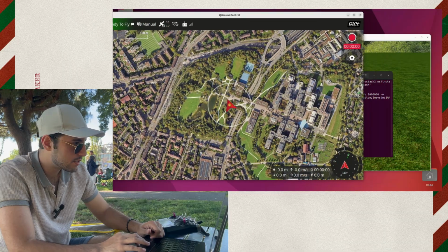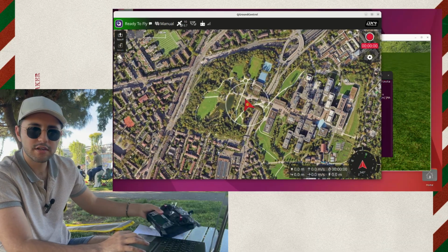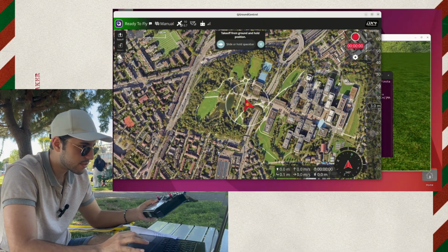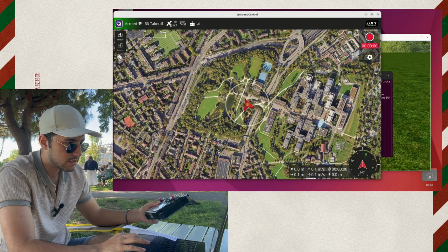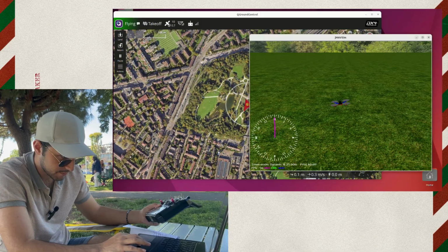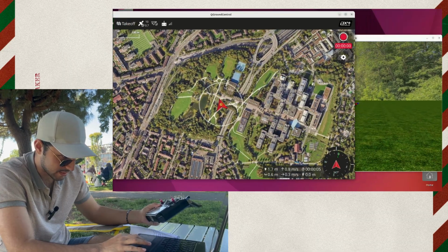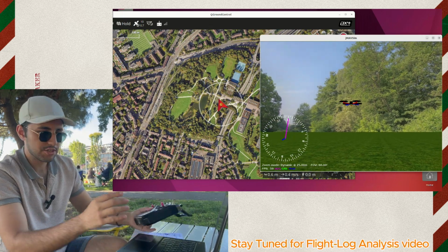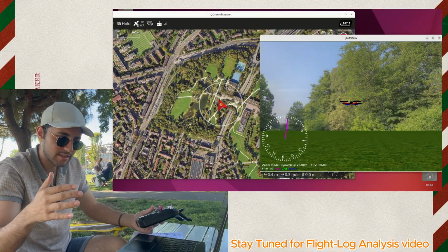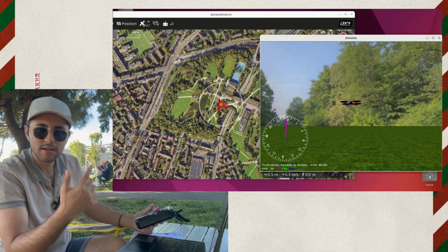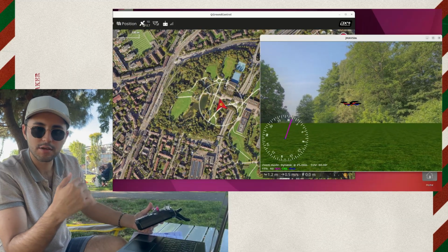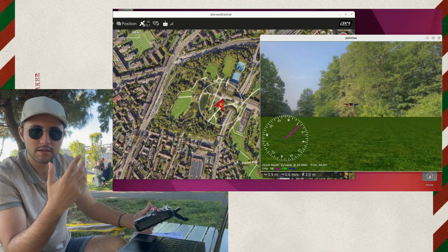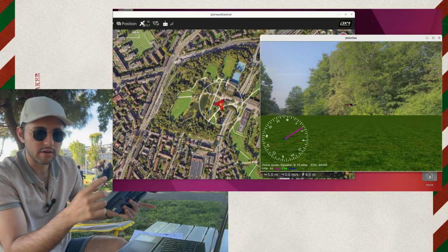Great. Now our simulation is connected, QGroundControl is connected. You see I'm not getting an error because my RC is also connected. I can get the transmitter data. Let's say I say take off. Can we see the drone taking off in the simulation? Amazing. You see, when the drone was taking off from the simulation, it had some lag. It just came to the left. This means the motor frame should have some modifications. Maybe you can change the PID values or use a better Kalman filter to reduce the error.